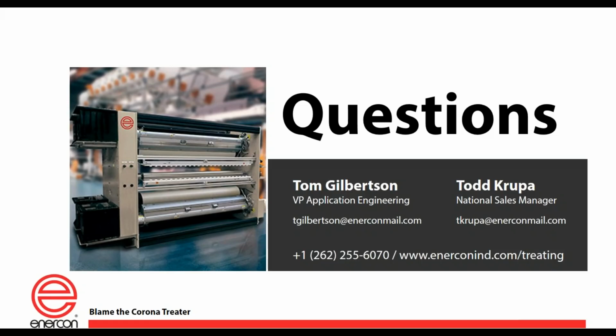For the guys on the other end of the scale, if you're in the desert in Arizona, you guys have the best deal ever. I've been out west and looked at some of our equipment that's literally 30 years old, and I'll tell you, that equipment looked great. It looked like it just got shipped, and that's because you don't have those troubles. You don't have corrosion, you don't have moisture causing high voltage arcing and all that kind of stuff that goes with it. So if you're in a dry climate, your maintenance load is a lot better, and likely you're not having the same issues with respect to operating the treater as your compadre on the other end of the country that might have a humid condition that they're operating in.